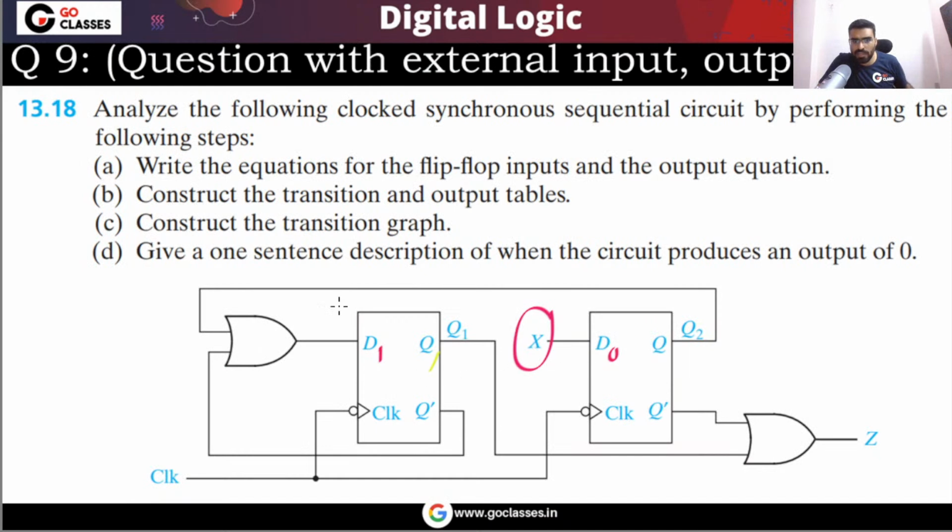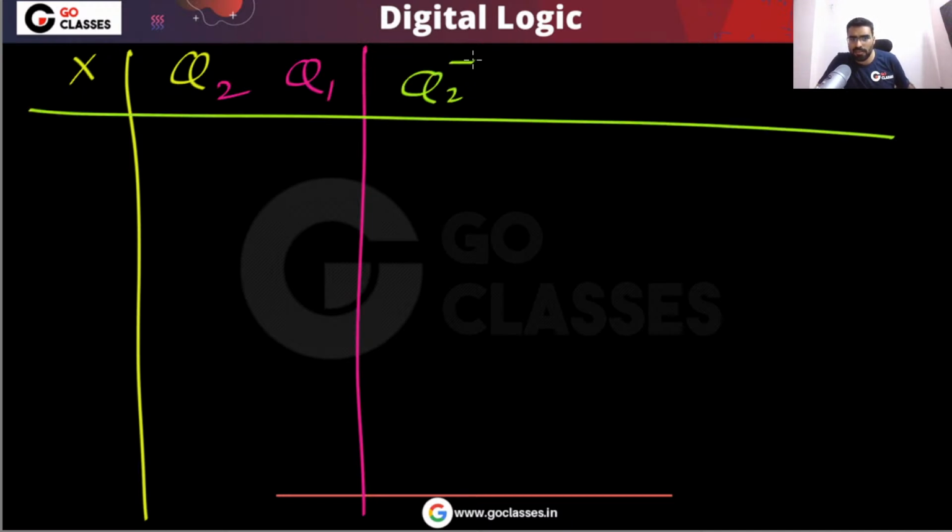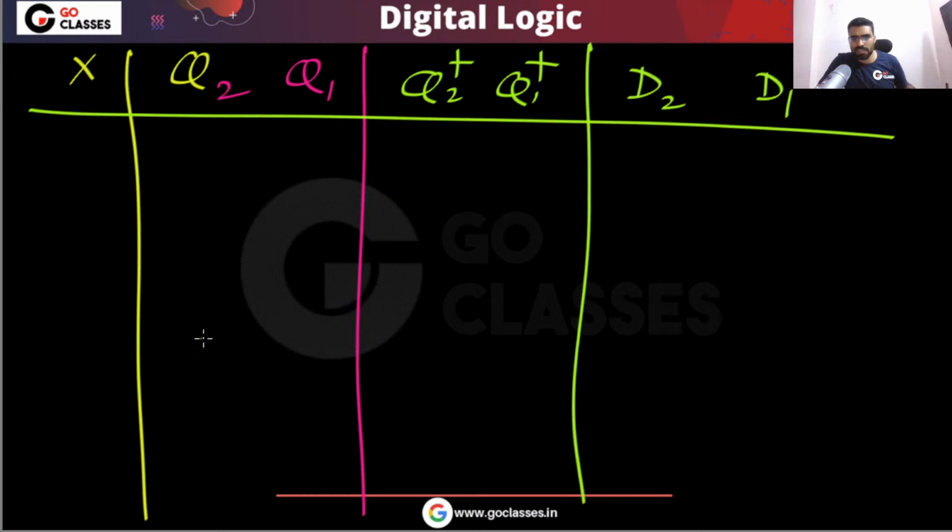I can call it q1, I can call it q0. The name is already there, so it is already called q1. So let me call it d2, and this is already q2. Now you can notice that you have q2 q1, and this x is there. From this you will find the next state. And what are the inputs? The inputs are your d2 d1. Only this will change, and your output is z. So this is the current situation.